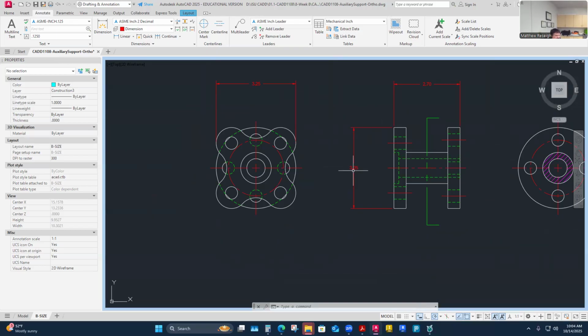This part is difficult because it's hard to say where the control is going to be established, because of the radius and the weird tangent radius features of the outer profile of the X plate. It gets hard to establish what the best datums or controls are going to be. I think for sure it's going to be center driven, just because of all the weird shaping of it.